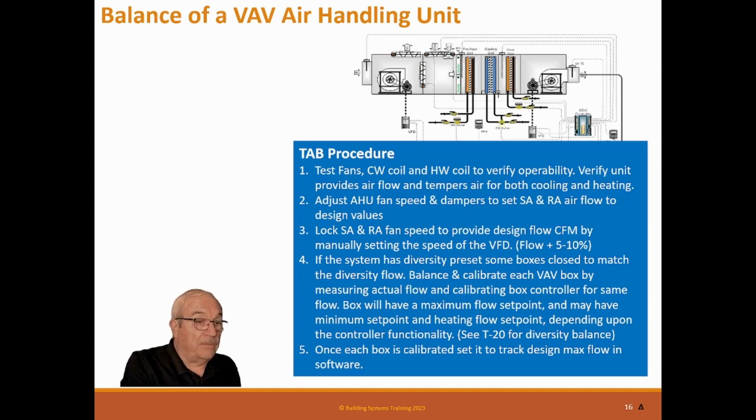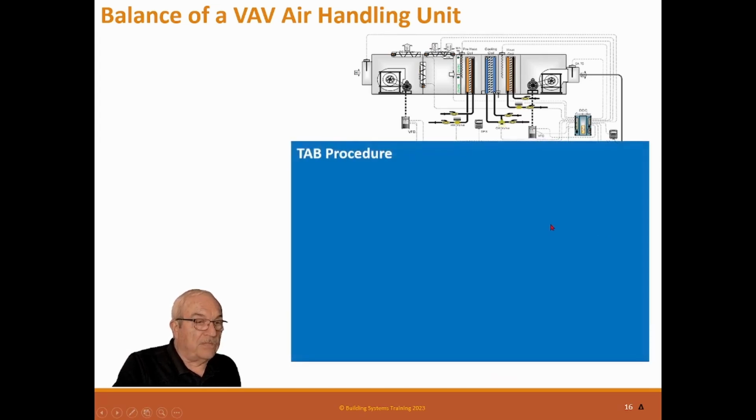It won't be right, it'll be reading it. Now you want to put a CFM so its reading will be correct, but what you're actually doing is calibrating that velocity probe, the velocity pressure probe. So once you input that into the box, it is now calibrated, like we said before in the boxes. Measure unit flow by duct.